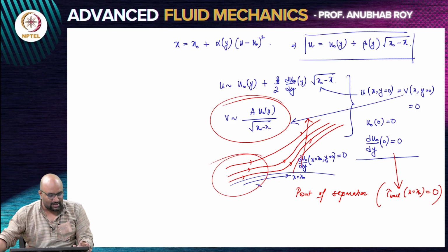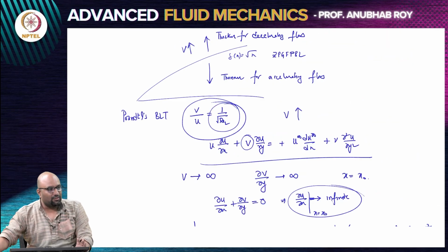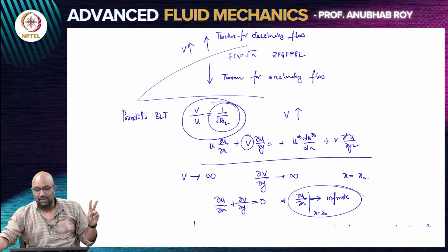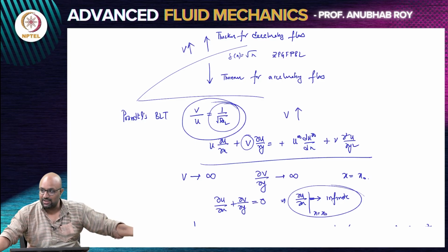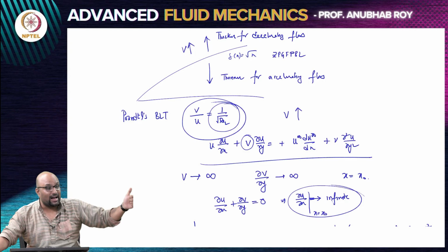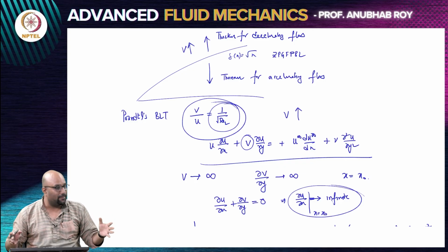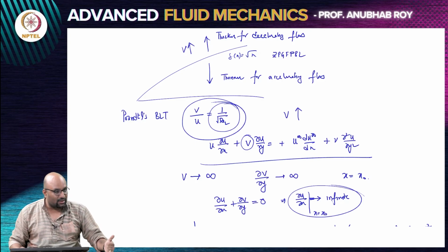We tried to arrive at this result by basically saying, we know that vertical velocities are going to increase. Decelerating flow has these two consequences. The shear stress at the wall is decreasing and the vertical velocity is increasing. So, as the vertical velocity keeps increasing without any bound, at some point the vertical velocity as you move along the surface is going to become infinitely large. When I use these terms infinitely large, I am viewing them again within the confines of Prandtl's theory. For full Navier-Stokes, there is nothing that is blowing up. Within the confines of Prandtl's equation, the vertical velocity is blowing up.